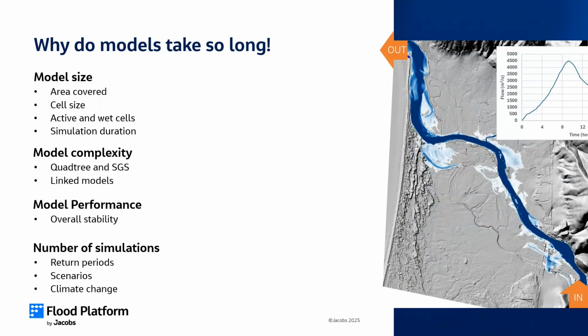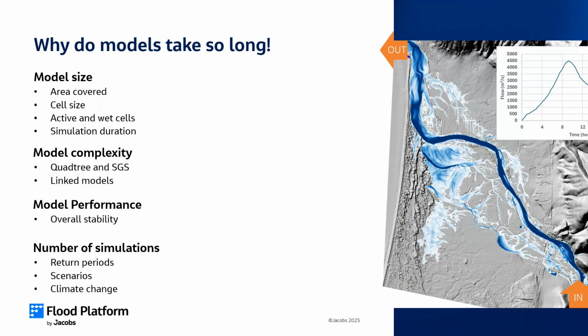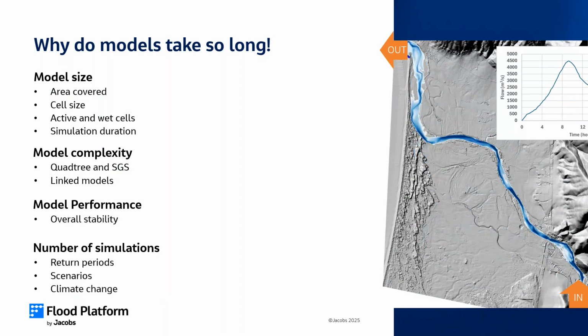Another issue is the simulation duration. Do I need to run my model for 24 hours, 36 hours when the peak is at 4 hours? Can I reduce the duration of my simulation and therefore reduce the amount of computational effort? Model complexity is really important.